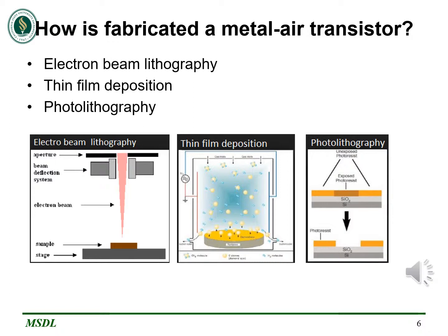In this project, a gate oxide thickness of 50 nanometers was utilized for gold and platinum devices. It was increased to 300 nanometers for tungsten to provide improved tolerance to the gate insulation. High-resolution electron beam resist polymethyl methacrylate was spin-coated on the pre-cleaned substrate. Spin coating was a two-step process to achieve a bilayer resist.